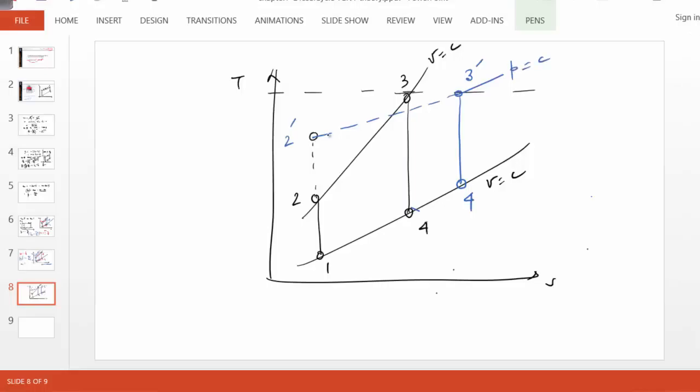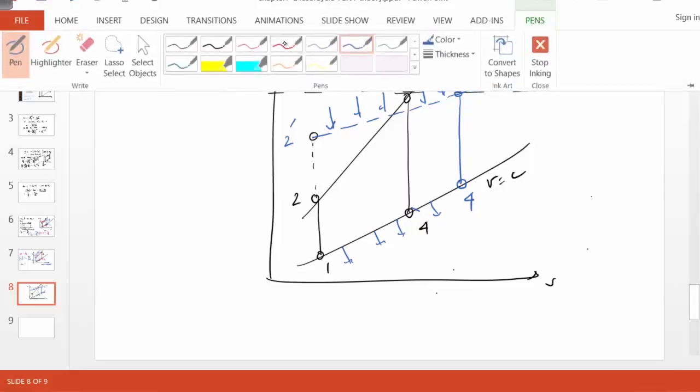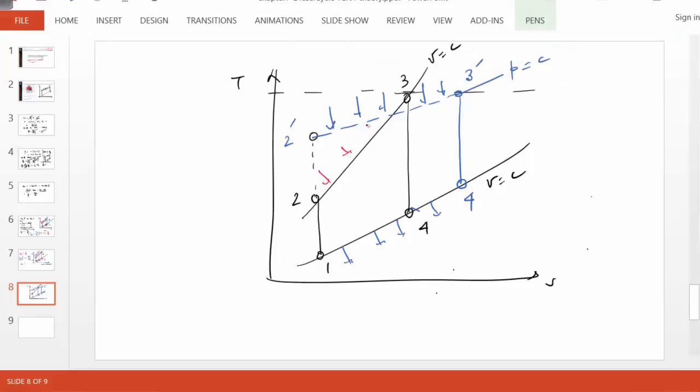So as a result, look at the temperature where the heat is added in a diesel cycle versus where heat is rejected, as opposed to that in a gasoline cycle, where heat is added generally at lower temperature. So based on where 3 prime is, you can show that the efficiency of a diesel cycle, because TC bar is going up, I shouldn't say equal, it's approximately equal, is 1 minus TC bar over TH bar. TH bar is lifted up in a diesel cycle.